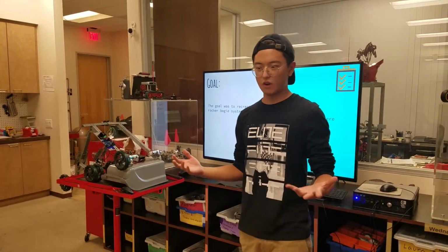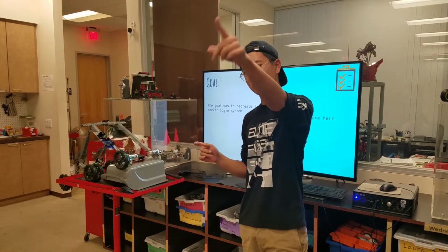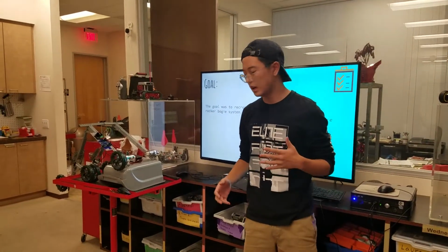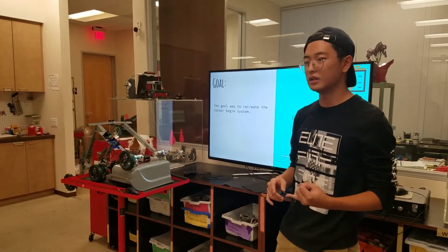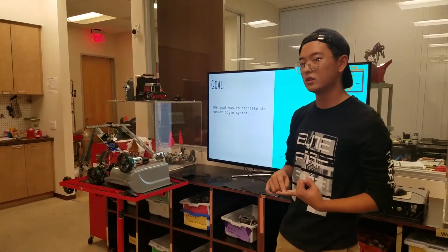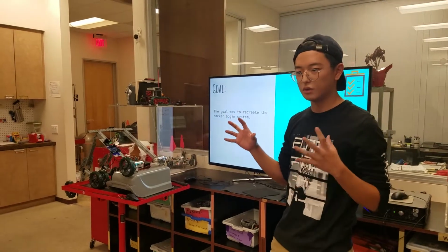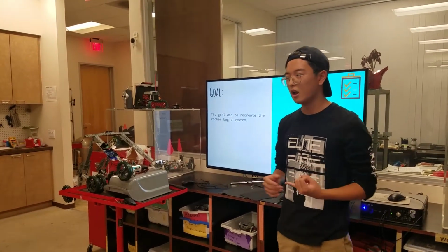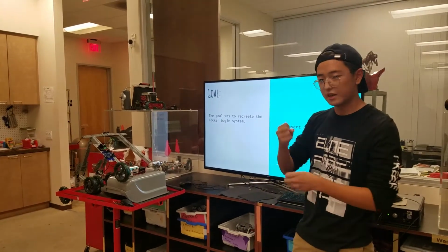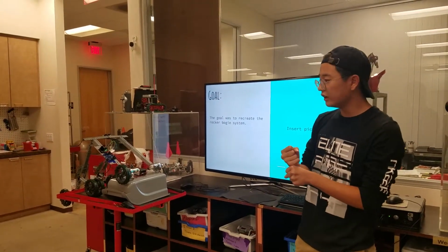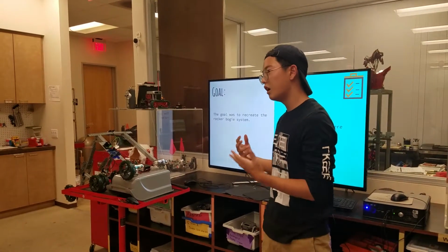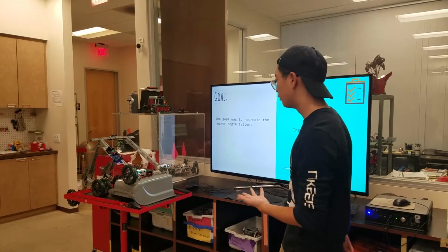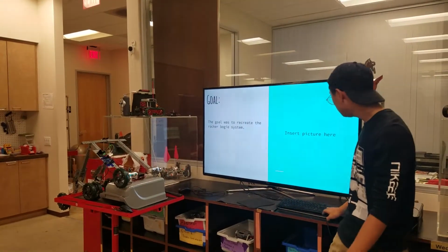And you might ask, what's the Rocker-bogie system? Well, it's right there, and it's used in the Mars rover. Basically it's a suspension system without using any tension like springs or hydraulics. When it's in space, you might have errors like a leakage in the suspension system, which you don't want. Or maybe over time, the suspension system gradually deteriorates. So what they thought was that you use pivot points instead, which last much longer, and it can have the same performance as a suspension system.